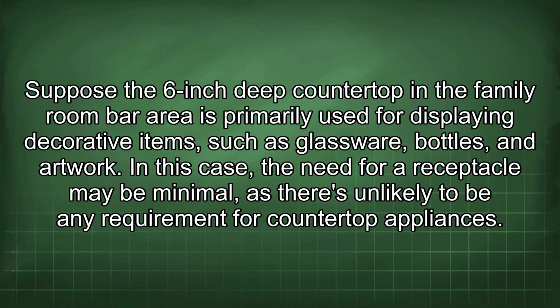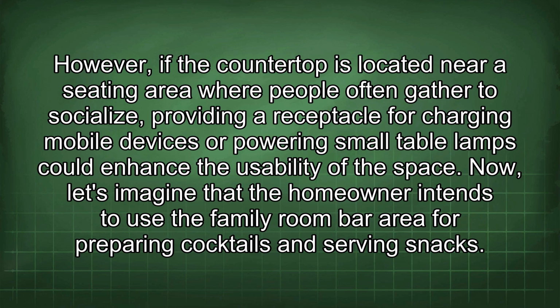Suppose the 6-inch deep countertop in the family room bar area is primarily used for displaying decorative items such as glassware, bottles, and artwork. In this case, the need for a receptacle may be minimal, as there's unlikely to be any requirement for countertop appliances. However, if the countertop is located near a seating area where people often gather to socialize, providing a receptacle for charging mobile devices or powering small table lamps could enhance the usability of the space.